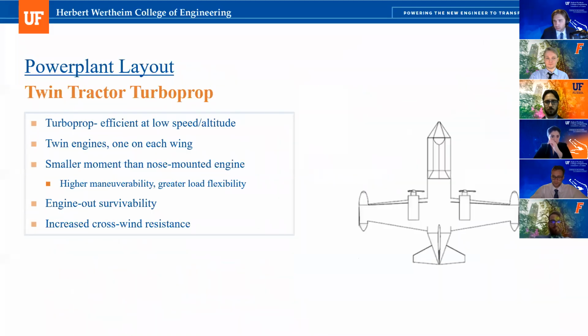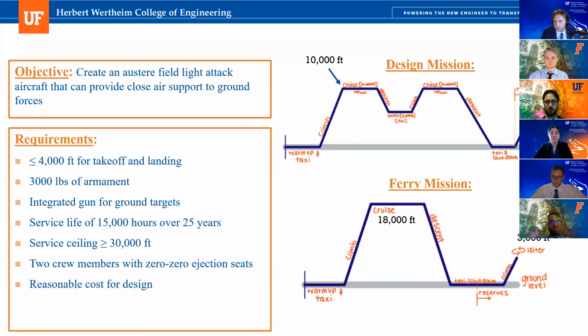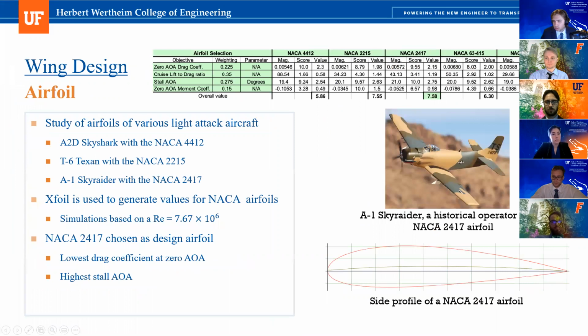That's very important information. That is like the guidance of the whole project. And then you start from wing design directly. So if you remember in this semester, from the initial requirement to the actual design of wing and tail and fuselage and landing gear and engine, we have an initial estimation based on requirements, right? So based on the requirements, let's say simply from the takeoff distance, landing distance, and like service ceiling, everything, we use that to have initial estimation.